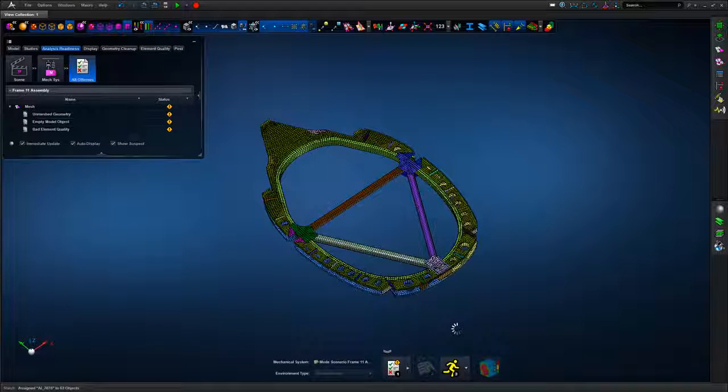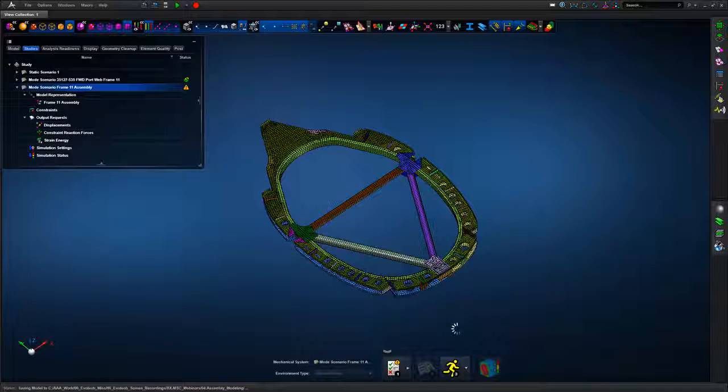We're now good to go from a normal modes verification run perspective. So we run the analysis, and if you remember, I was talking about computational parts earlier. Any parts or sub-assemblies which we've verified in the background prior to this point, that structural or matrix definition, if you like, from an FEA perspective, has been stored internally and will speed up the full solve.